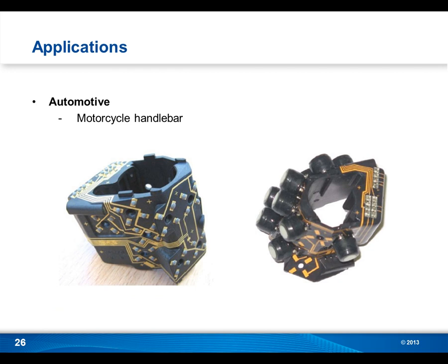It allows you to do a 3D ergonomic design and put this directly on the structuring. If you can imagine bending a flex circuit or some sort of wiring harness around this small three-dimensional part, it would be very difficult. So LDS comes into play here very well, and this incorporates full 3D manufacturing. This is done with a 3D pick-and-place machine, and the solder is put on in a 3D pick-and-place environment.